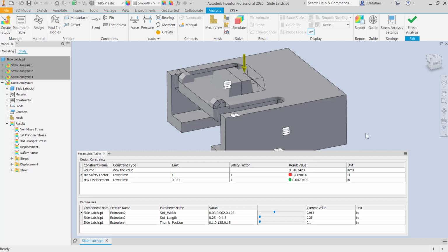Now when we see a lower safety factor, we automatically assume we need to add more material to beef this thing up. But actually on this problem it's just the opposite. We need to weaken it so that it is easier for it to push down, so that it doesn't generate as much stress. And then also the stress itself is limited to a very small area around this arc, so it may not be significant as long as it doesn't go all the way across between this arc and this arc over here. But let's examine some of the other settings.